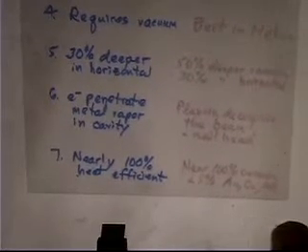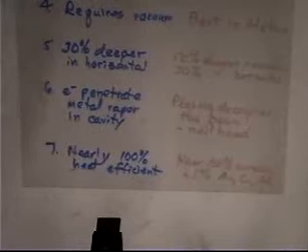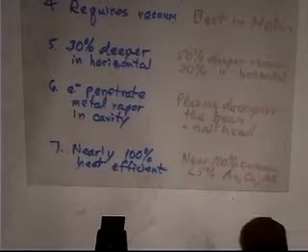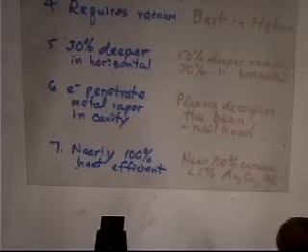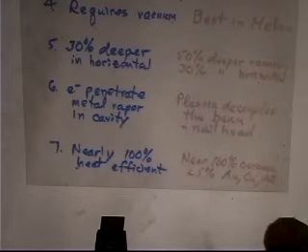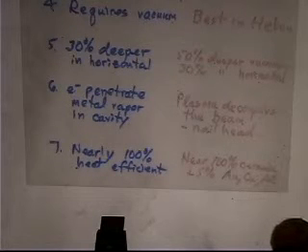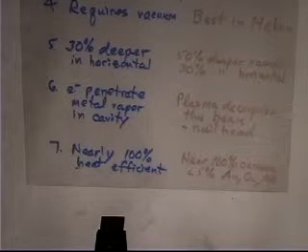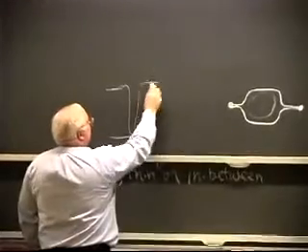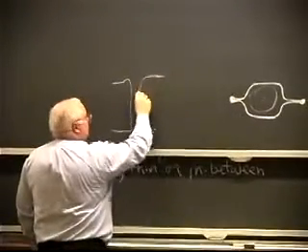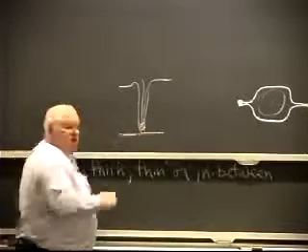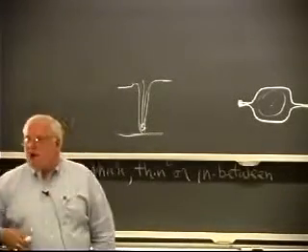Number 5 is that if I make a laser weld, and let's say it's 1 inch deep in the vertical position, it'll be 1.3 inches deep if I turn the thing on its side and shoot it horizontally. And the only reason for that is if this is my cavity, and you've now seen the movie that Chris likes so much, I've basically got liquid slumping down and falling into the bottom of the cavity, and I keep on having to blow that liquid that falls in the bottom away.